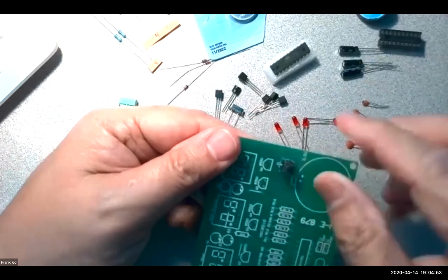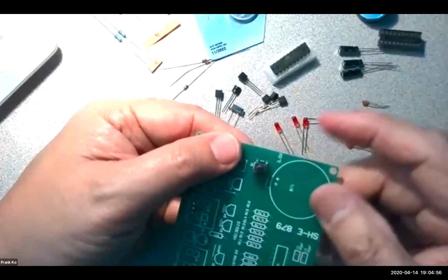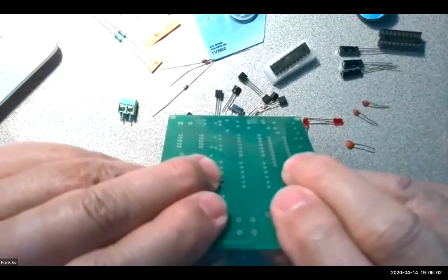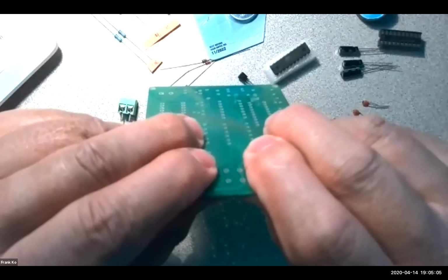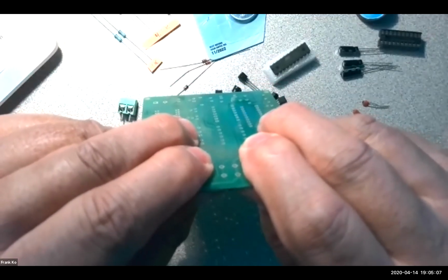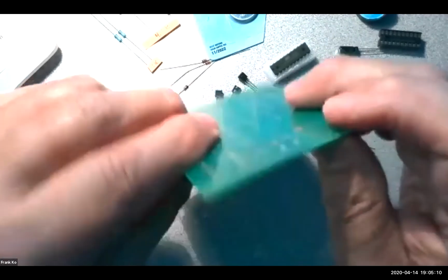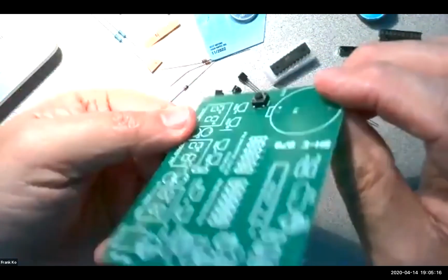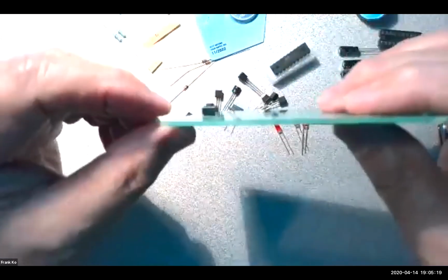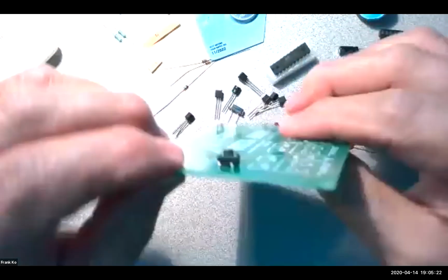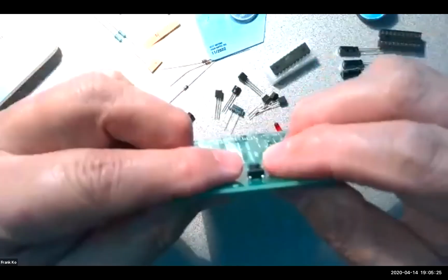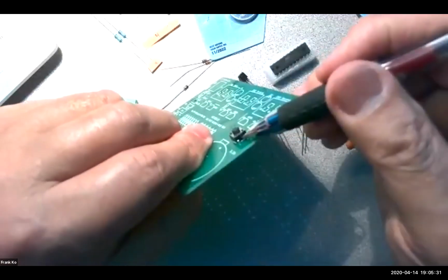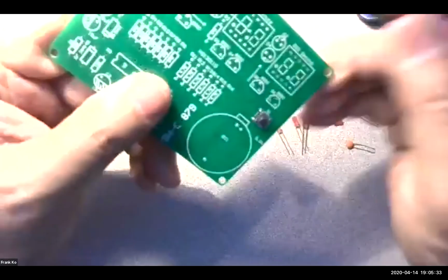Those pins have to be on the left side and the right side as you put the switch onto the board. Now you're going to have to give it a little bit of encouragement in order to get the wires of the switch through the board. So just gently press, gently press, gently press, and you can see the wires poke through, and the switch is flush onto the board. You want to make sure before you gently press it in place that the wires for the switch come off the right side and the left side.